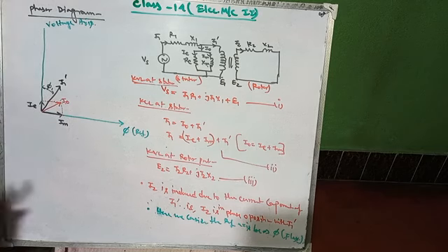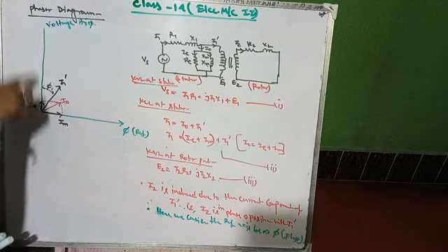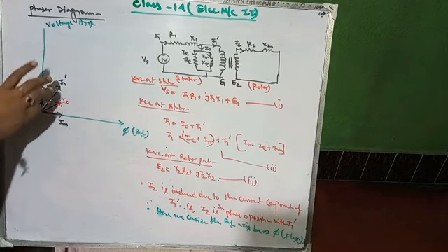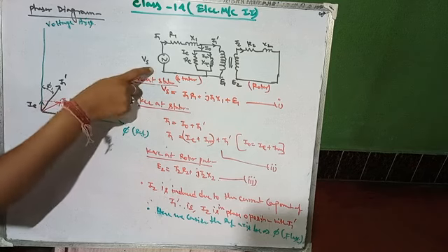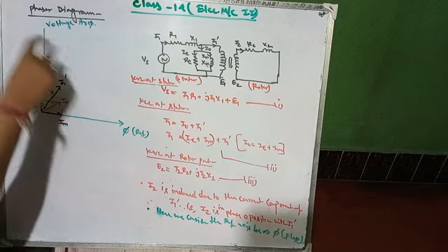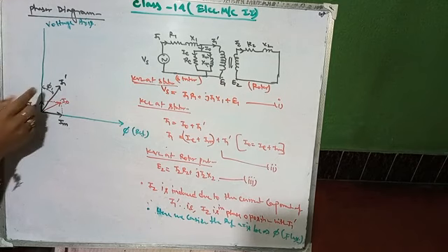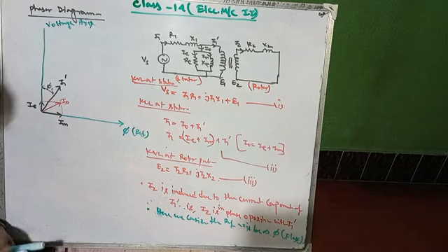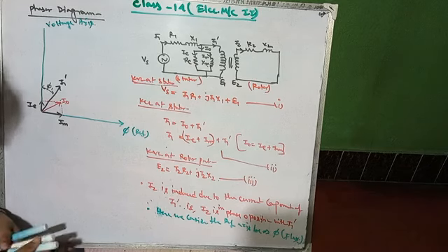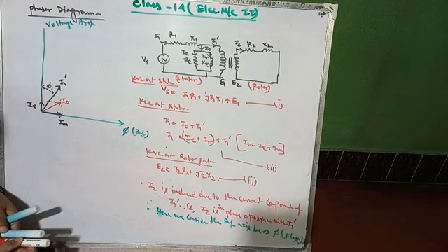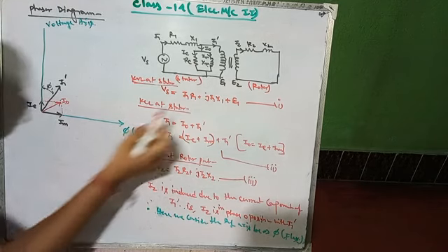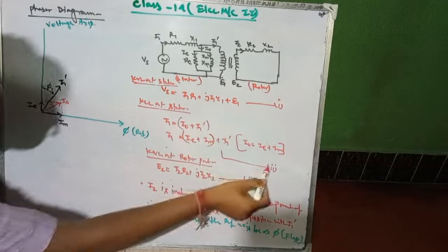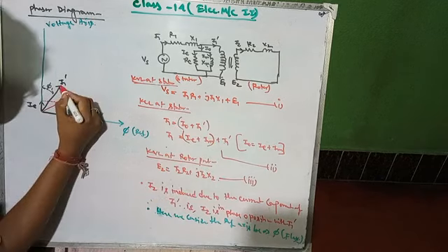Okay, so now this phi 1 is not lagging from this voltage axis. Whatever the voltage is induced over here, that is Vs or E1, you can say. From this type of voltage, the I1 dash is always lagging by some angle phi 1. Then you have to add again. So how to add? If we add I1 dash and I naught, then the second equation will be developed.